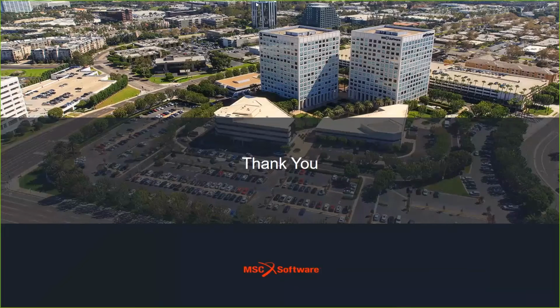There are a lot of other companies that can also do this kind of tire testing. With my experience with tire manufacturers, they'll provide some basic Pacejka parameters, magic formula parameters. But anything above and beyond that, like FTire, needs a separate test to provide those parameters, which is usually requested by car manufacturers, truck manufacturers, or construction equipment manufacturers as well.